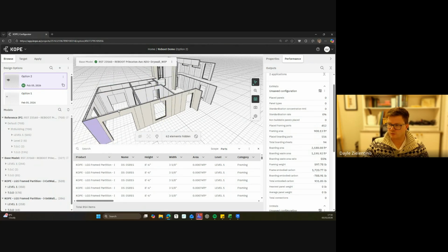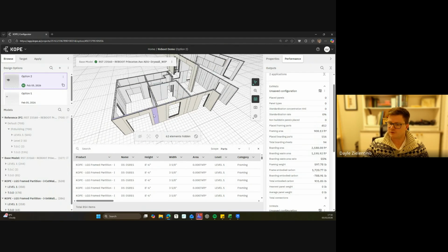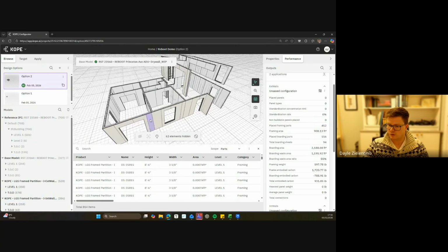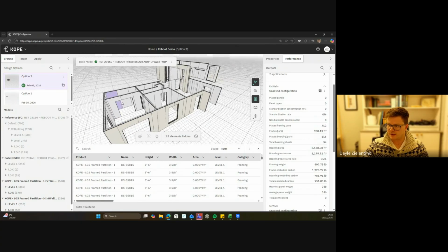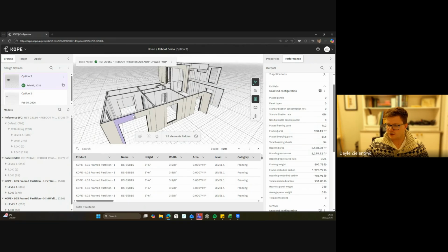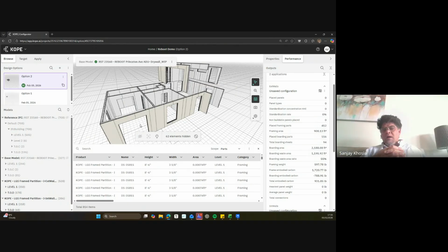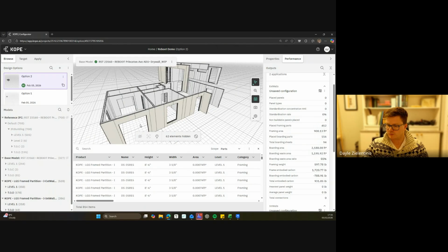And that comes down to the factory. What you're trying to do is optimize the size of the mod to fit on the back of a lorry, and then help the factory be as efficient as possible with their installation of the pieces and parts inside that. So if you're getting some repeatability, maybe they're happy. Other manufacturers don't care about repeatability because every single panel has to be signed off regardless. If it's 10 of the same panel, they would sign off every panel as if it was unique each time. Others sign off 1 type and that's it. Great, we're done with them. We don't need to sign off the other 9.